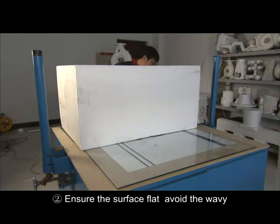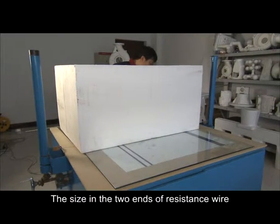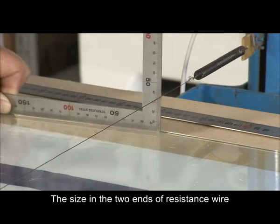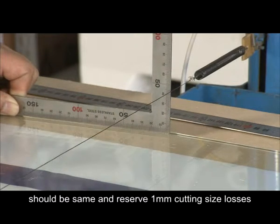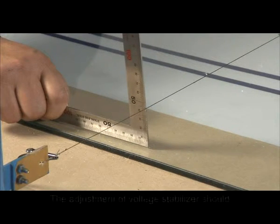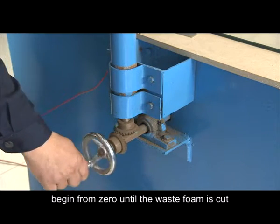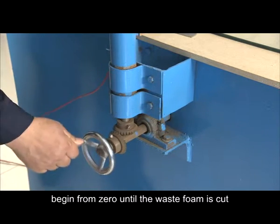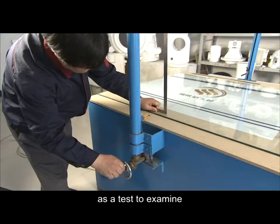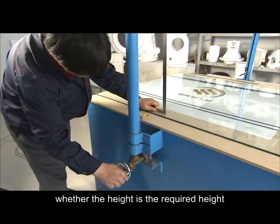2. Ensure the surface is flat. Avoid wavy stitches and uneven pattern height. The size at the two ends of the resistance wire should be the same, and reserve 1 mm for cutting size losses. The adjustment of the voltage stabilizer should begin from 0 until the waste foam is cut as a test to examine whether the height is the required height.